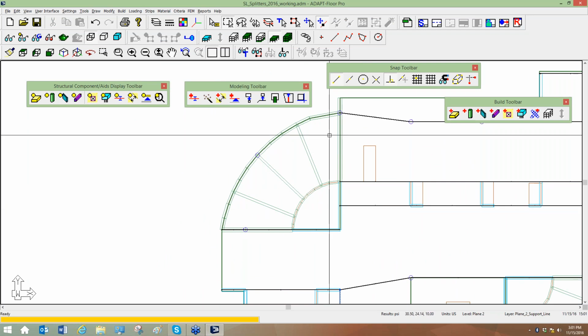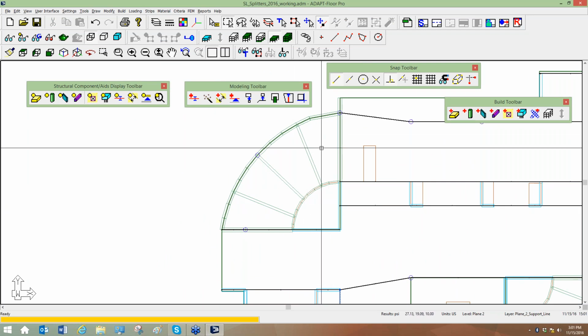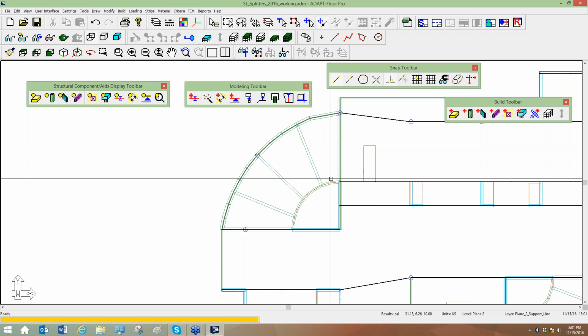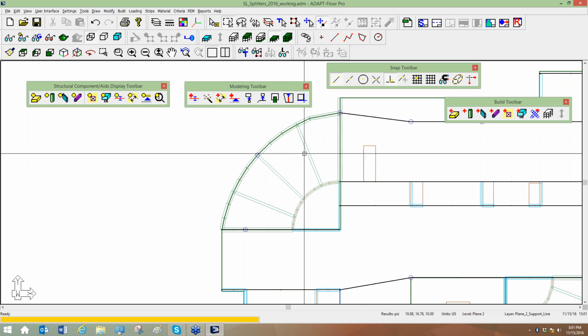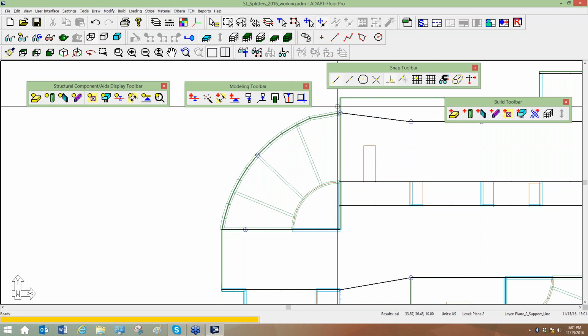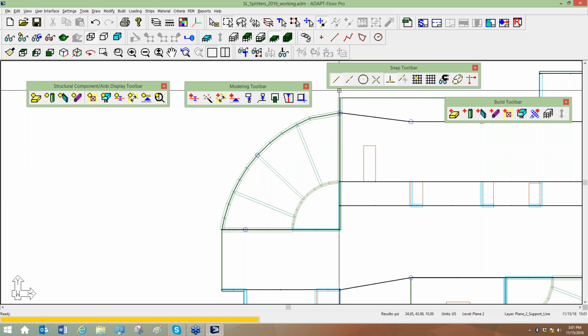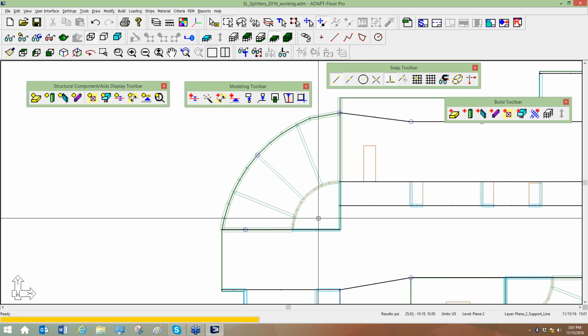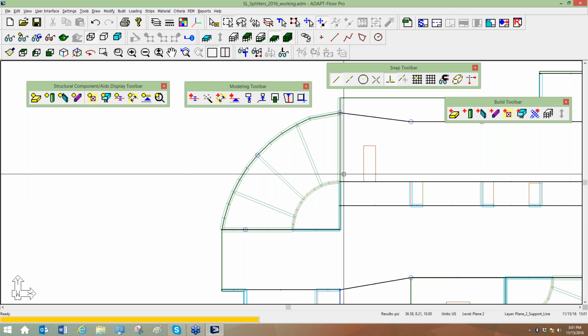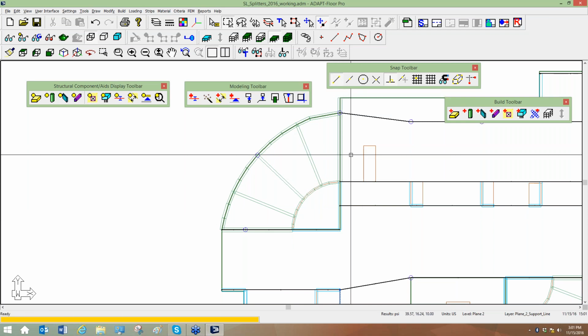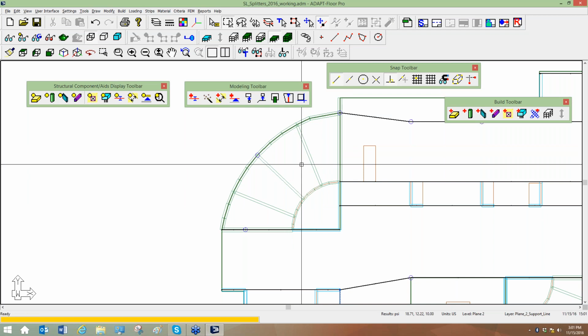Because we want to bound off this zone and not have those strange tributaries created that overlap into this zone, we want to have those kind of self-contained, if you will. I'm going to add a splitter along this boundary. So I'm imposing on the program to stop the tributary along this boundary because we clearly saw that it leaked into this area.